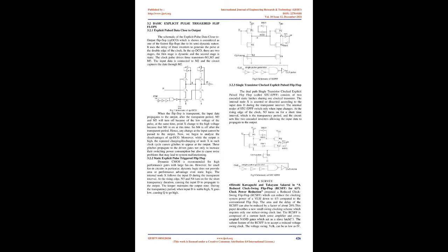The RCSFF is composed of a current latch sense amplifier and cross-coupled NAND gates which act as a slave latch [2-3]. A salient feature of the RCSFF is to accept a reduced voltage swing clock.